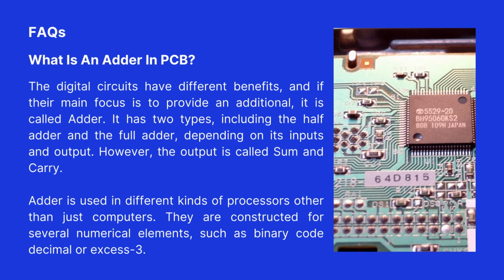It has two types, including the half adder and the full adder, depending on its inputs and outputs. The outputs are called sum and carry. An adder is used in different kinds of processors other than just computers. They are constructed for several numerical elements, such as binary code, decimal, or XS3.